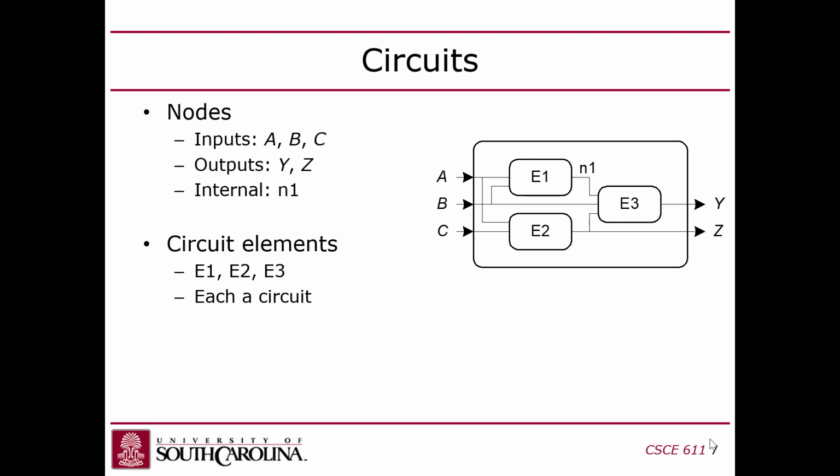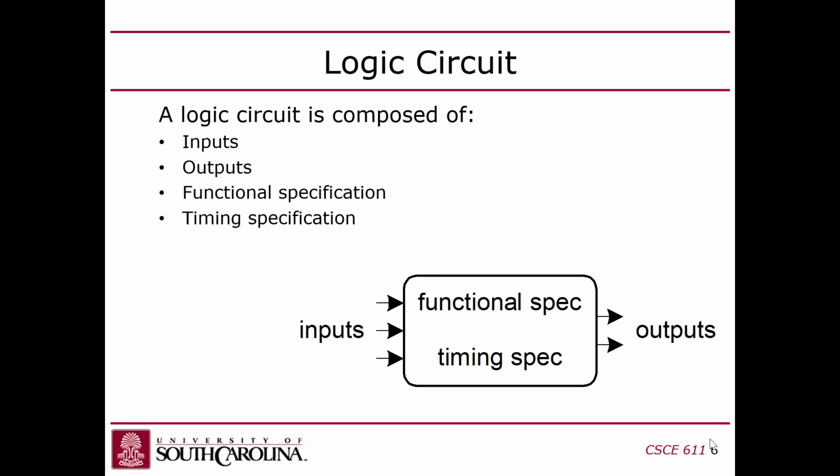Now, when you drill down inside of a logic circuit, this slide is showing it sort of as a black box. So you can see the inputs, the outputs, you know what it does, you know how it performs, and what the timing constraints are. How long it takes for outputs to change whenever you change an input, for instance. That's part of the timing specification. But this is the information that you would give to a user who wanted to use your logic circuit. This is kind of an interface spec.